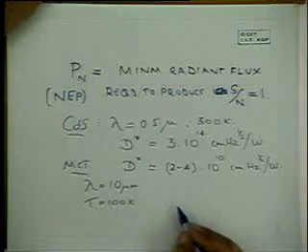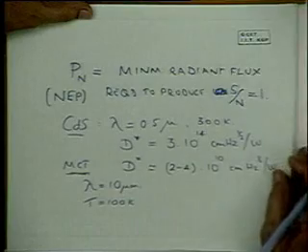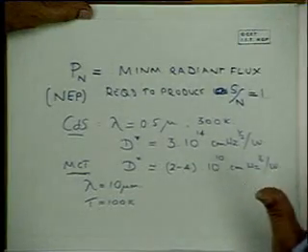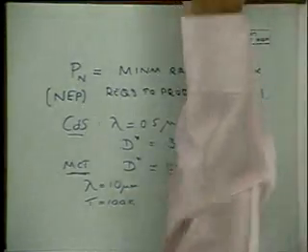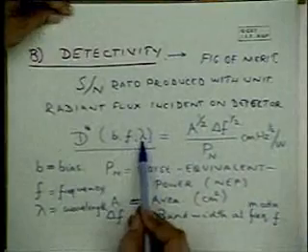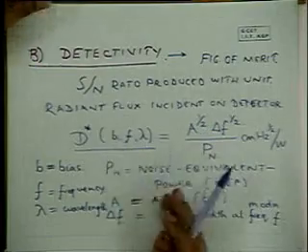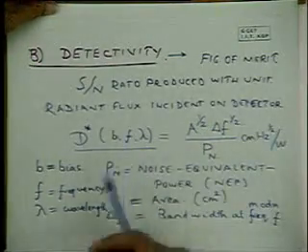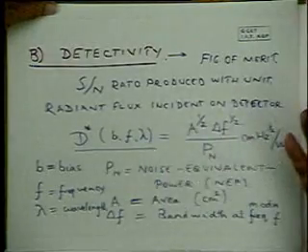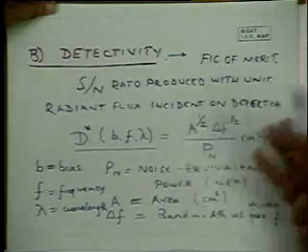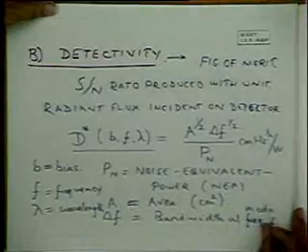The question was, is this material dependent or device dependent? It is both material dependent and device dependent. It is also wavelength dependent, like I've put here. It depends upon the modulation frequency. It depends upon the bias, and it's obviously a function of temperature, because in a semiconductor, as temperature increases, carrier concentration increases. Generation-recombination noise increases as a function of temperature. So it's very strongly a function of temperature also.